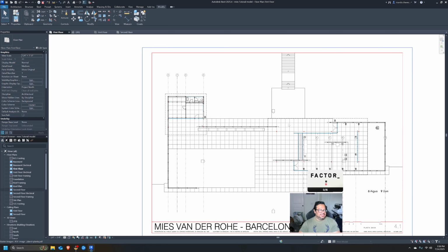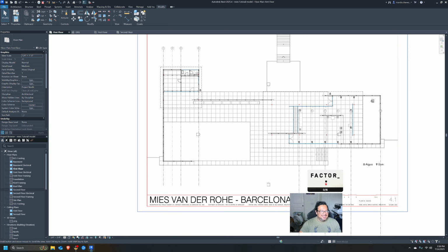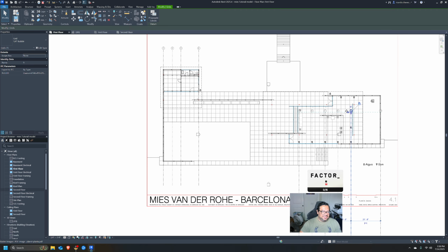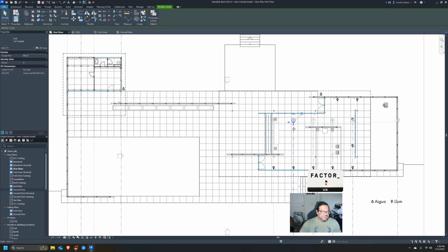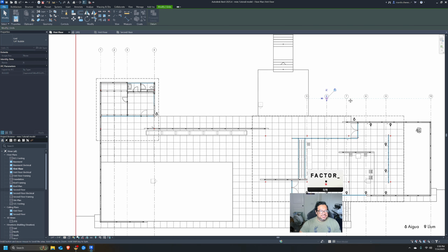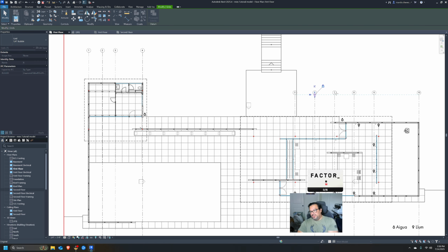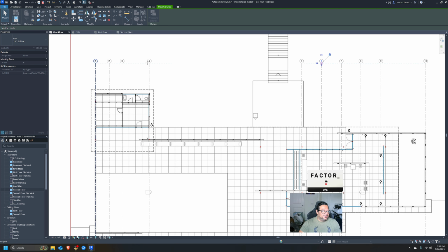So you can kind of see it looks all funky, right? What we can do is, since all the grid lines are 3D linked, you see here we have them here. We can click on one and drag it, and it moves all of them to the top, right? So it's helpful because you just want to place them quick, but you want to be able to keep them straight. So we can drag them everywhere, and then we'll click.